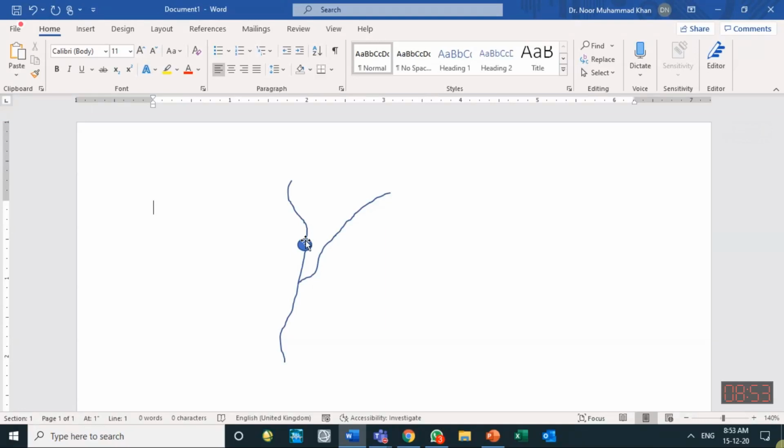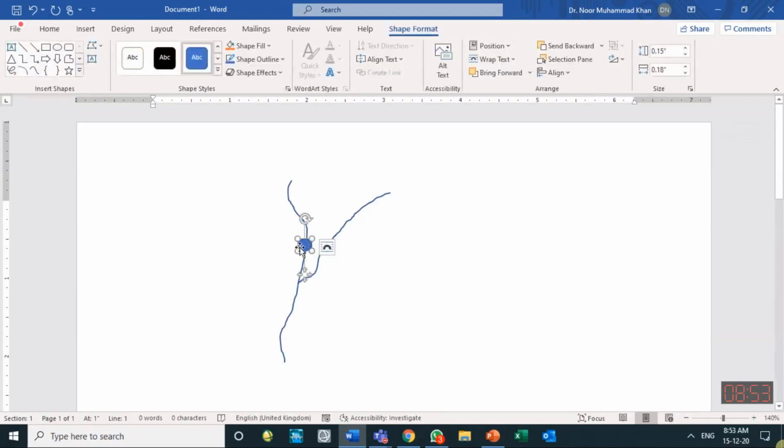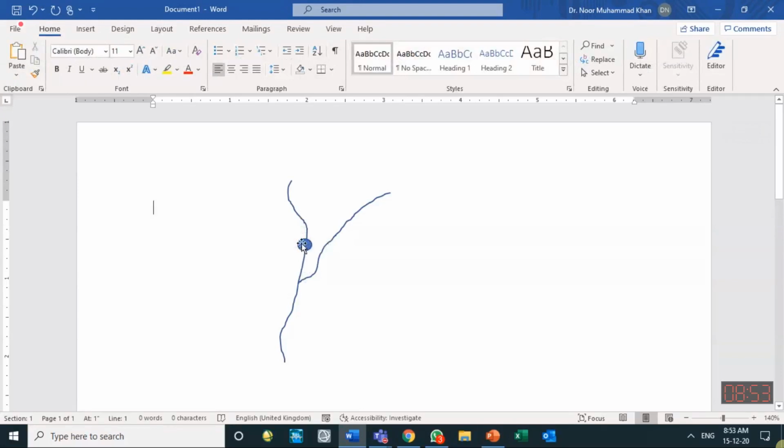So if I have measured a water level at this stream gauging station, and the water level at this location was wrongly increased because of this downstream tributary, the effect of this downstream tributary has risen the water level to a higher elevation, it means I will be giving the wrong message to the people that more flow is passing over here. Over here, all the flow was coming from this tributary.